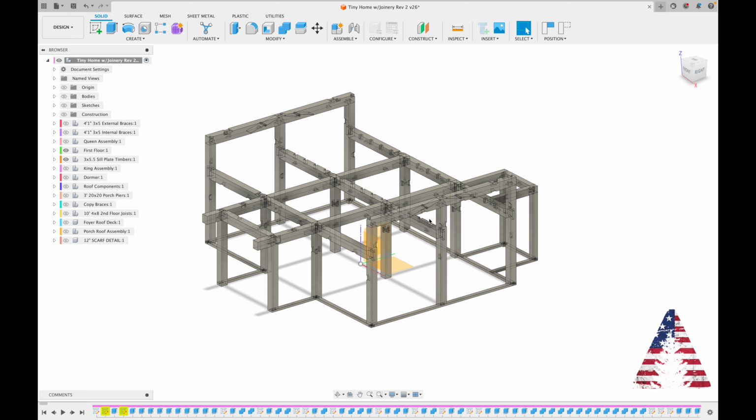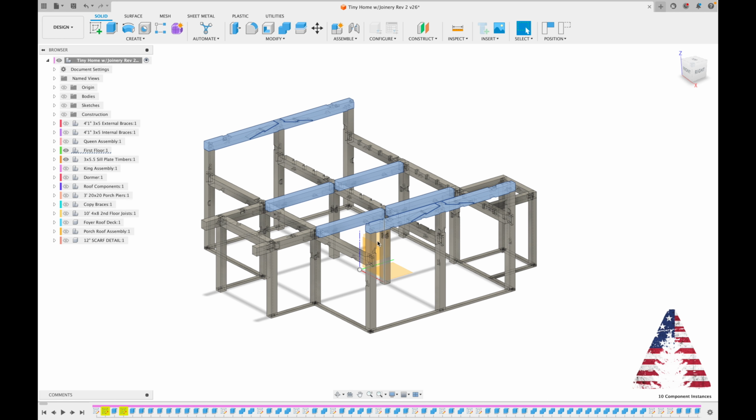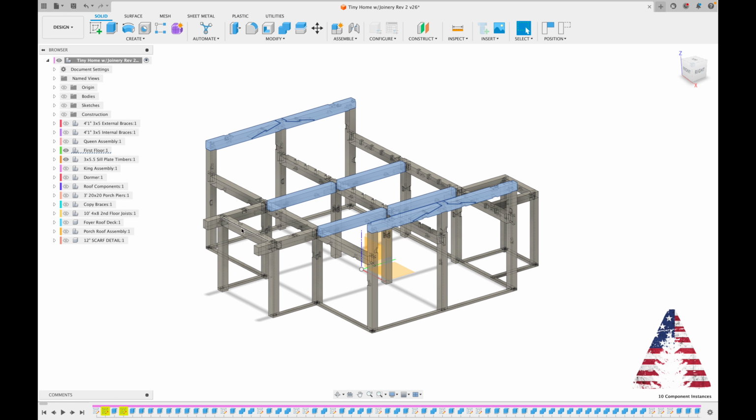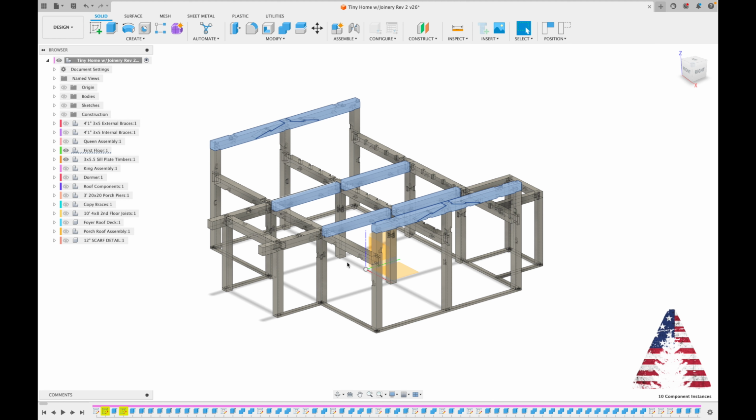And at that point, once those 3 rows are raised, we can attach the kind of tying structure here, as in these purlins here and these summer beams. With all of their associated braces, at that point, this is a very rigid structure, and we can build off of that. It'll be all tied and integrated together. This is completely standalone. No roof would be tied to it, but this is very much a strong structure. And we can work on the mechanical room and the entryway later, because these tie in simply after the fact. So we can work on the main structure first.